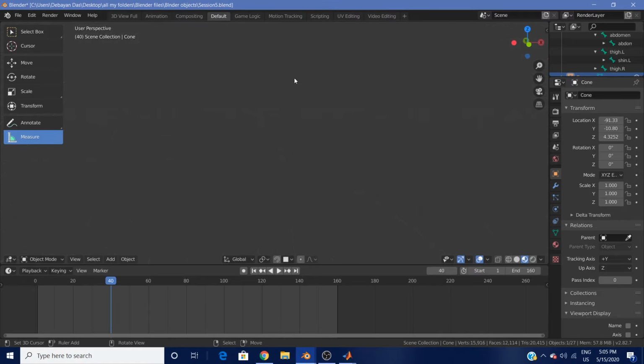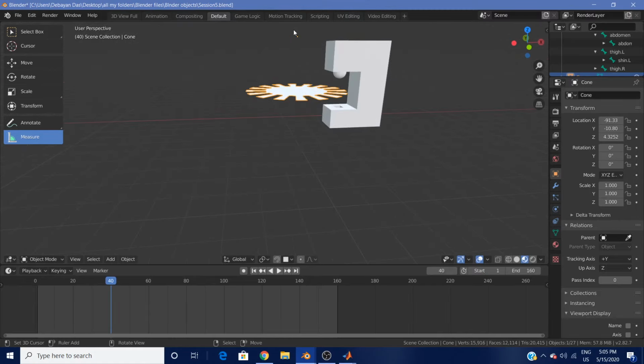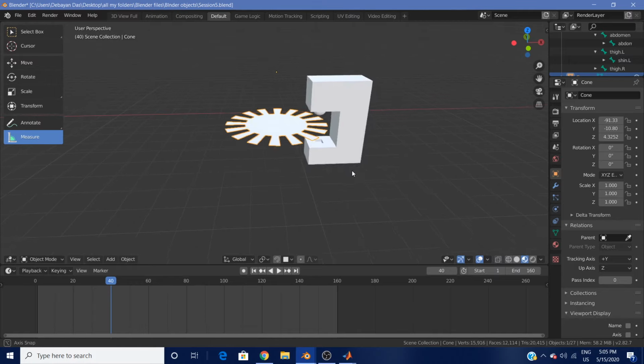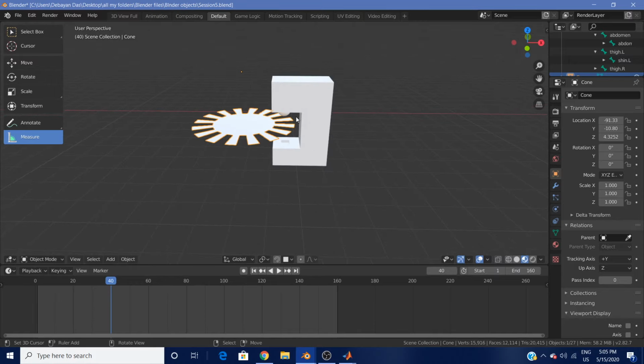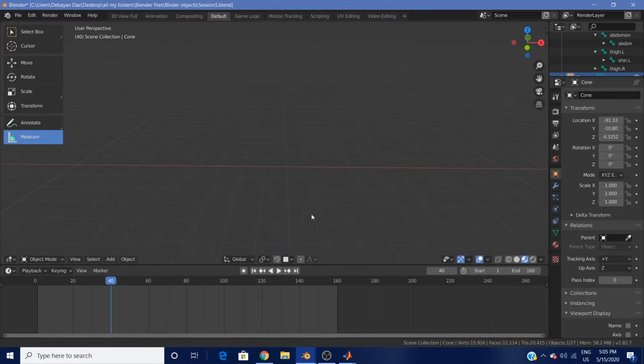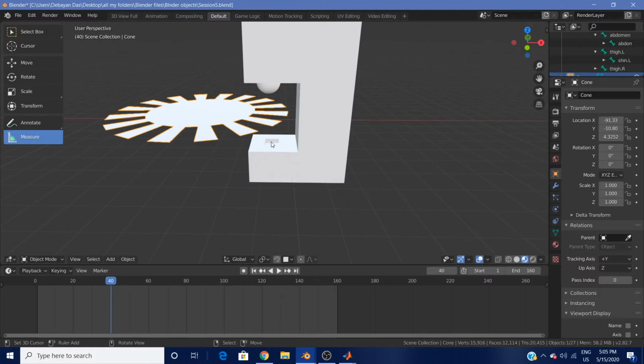So if we had some wheel and axle connected, with a motor on top over here, we'd have this connected to the shaft so that this rotates, and whatever is being rotated would be down here. When this rotates, it would pass through a device that would probably have a laser or an optical emitter, something that gives out light over here, and we'd have a sensor right here, and this sensor would calculate the number of times an opaque disc cut that laser.